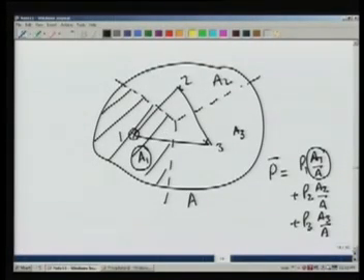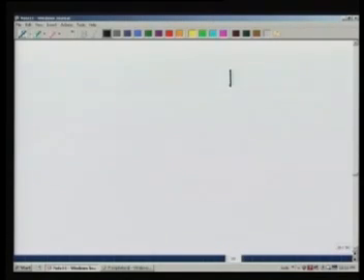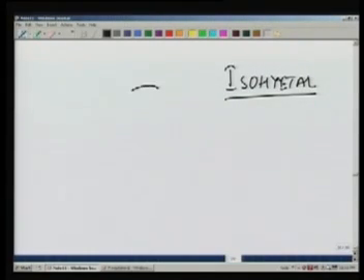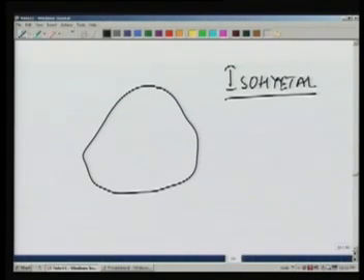For example, there may be mountainous area here and there may be plain area here. So if there is a sharp change in elevation, the Thiessen polygon method will not be able to account for it, and therefore we have another method which is called the Isohyetal method, which accounts for the variation of topography also by looking at individual precipitation values and drawing isohyets. Isohyets are nothing but lines of equal precipitation.